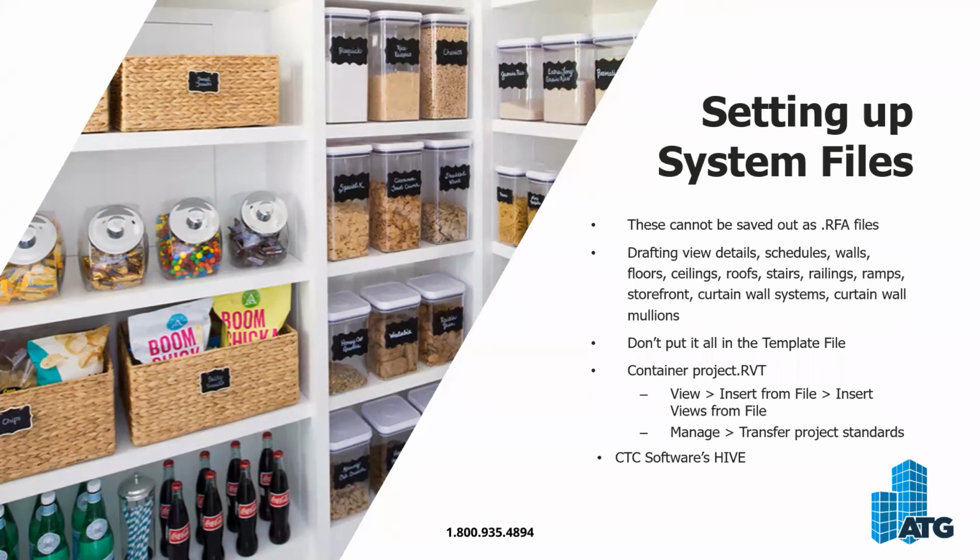What goes in your Revit template file is only your almost certain to be used families. So you only put in your 4 7/8 inch, half inch or 5/8 inch chipboard on metal stud wall. That goes in your template because you use that almost certainly. That's what goes in there, not all of the 77 other wall types that you utilize.